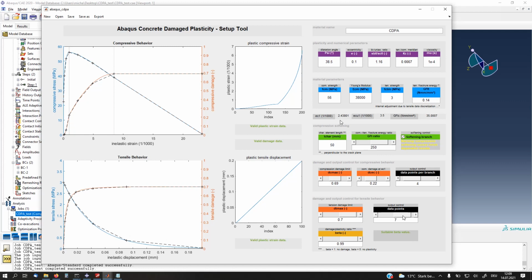All right, I think that's everything you need to know about this. Once again, just always start with the material parameters, with the compressive strength. If you're not sure about all the other values, just stick with the initial ones, because for the lower strength concrete, these values are computed with equations that you would probably use yourself, like the Model Code equations, but also the ACI equations, especially for the Young's modulus.